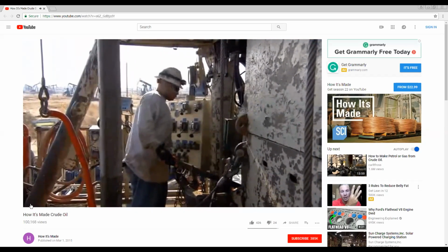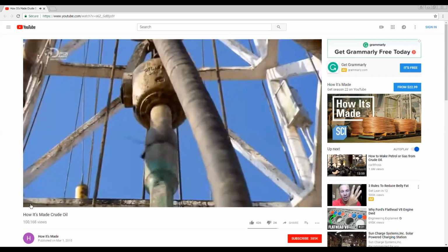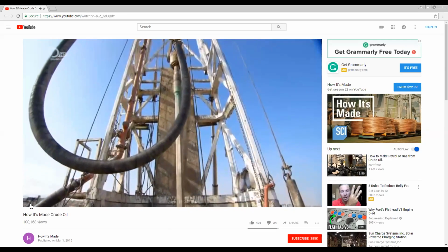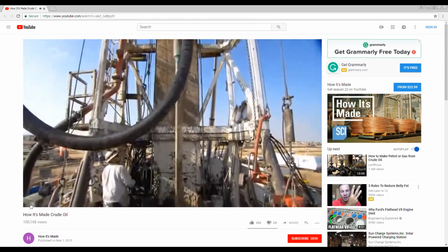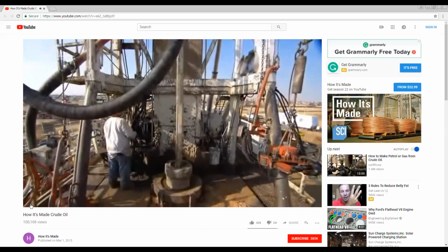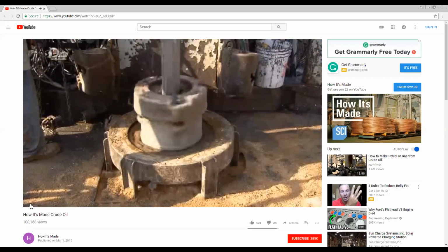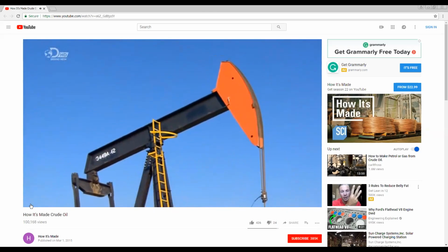Once the drill pipe descends its full 9-meter length, they connect another pipe. The process is repeated with subsequent drill pipes until they bore into the reservoir containing fluid. Throughout the drilling process, they pump a mud mixture down the drill pipe. It comes out the drill bit at the end, hits the bottom of the hole, then backs up to the top. This process brings back the drilled out rock.